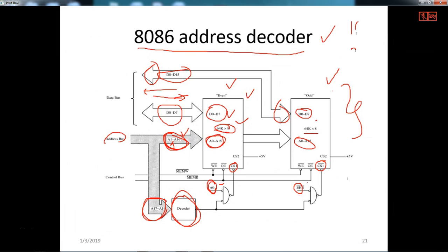So that means if a question is, or if you want to design a system so that the code segment can start with 10000H, that is what you need to do. So then the fundamental connections are this, right? So code segment and data segment can overlap because of 64K. So within a segment you can define these two. That is what is done in the lab trainer kit.